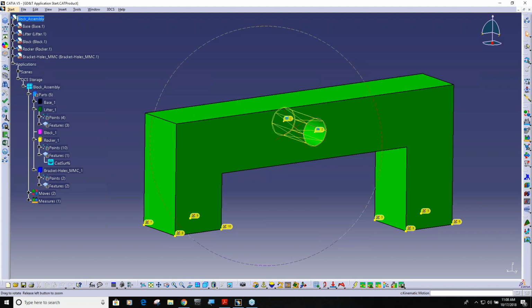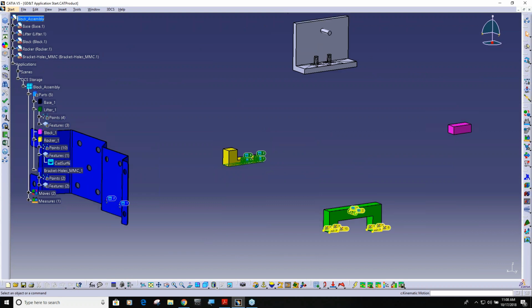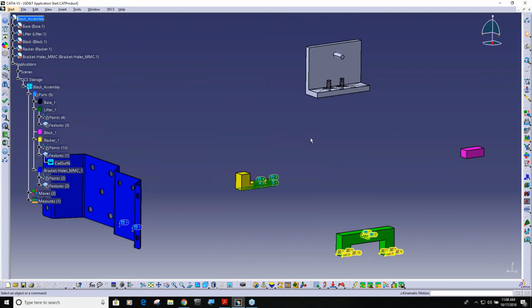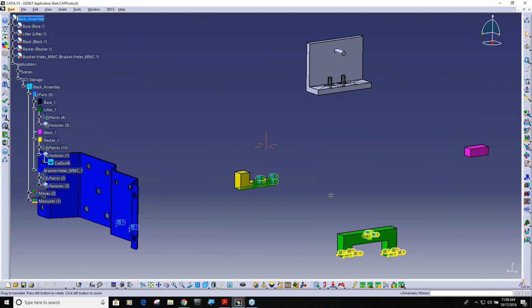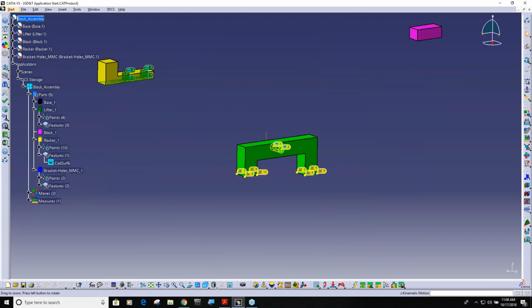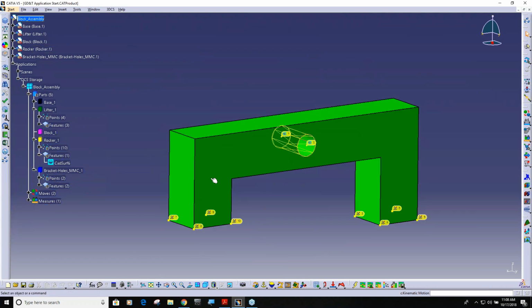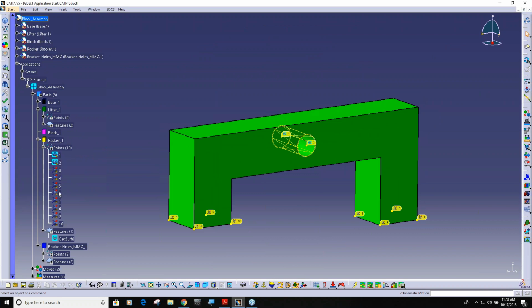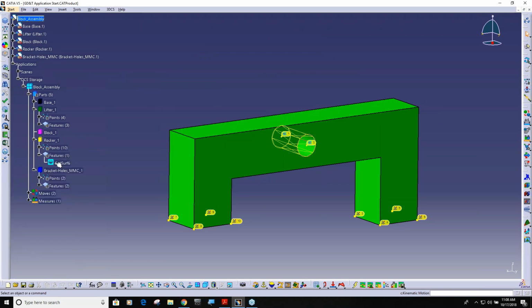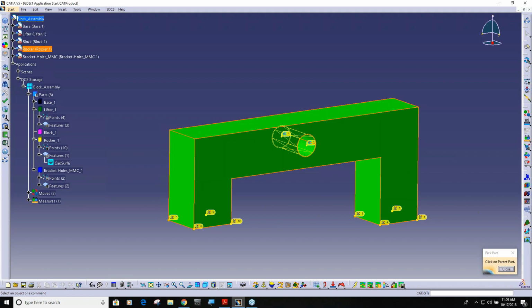So I'm going to start out. You can see I have a model. I basically mixed a bracket model with our feature-based modeling, just because it's easy. And if we look here, you can see that in my rocker, I have one feature, I have a bunch of DCS points, and there's no tolerance on it. So to talk about linear dimensioning, I'm going to, by the way, do all of this with our new GD&T tolerancing function.